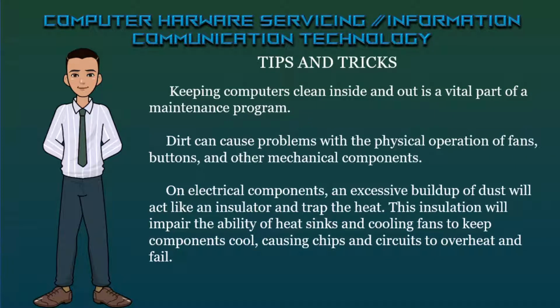The next topic is about tips and tricks. Keeping computers clean inside and out is a vital part of a maintenance program. Dirt can cause problems with the physical operation of fans, buttons, and other mechanical components. On electrical components, an excessive buildup of dust will act like an insulator and trap the heat. This insulation will impair the ability of heat sinks and cooling fans to keep components cool, causing chips and circuits to overheat and fail.